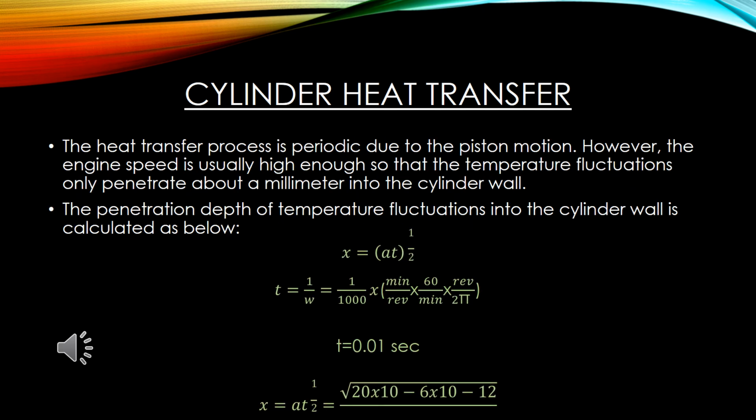The heat transfer process is periodic due to piston motion. However, the engine speed is usually high enough that the temperature fluctuations only penetrate about a millimeter into the cylinder wall. The penetration depth of temperature fluctuations into the cylinder wall is calculated as below. I put some formulas for you.